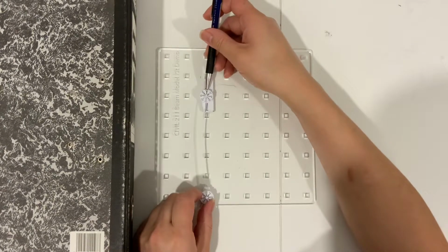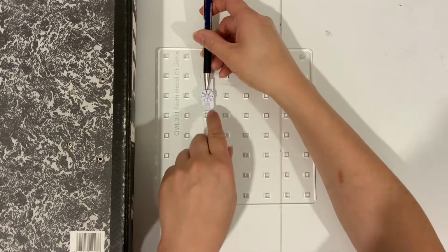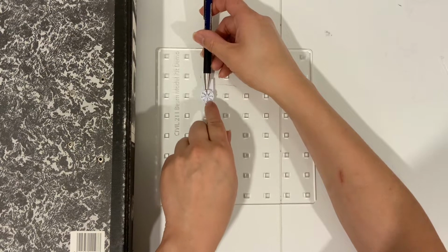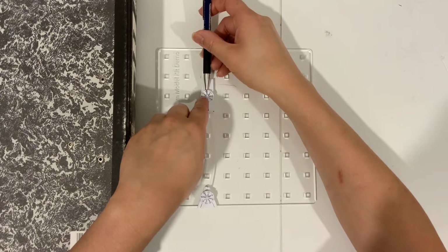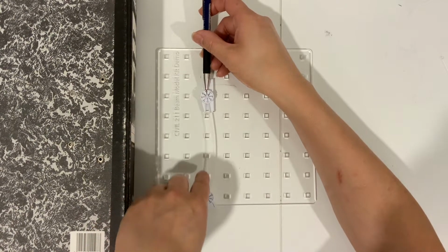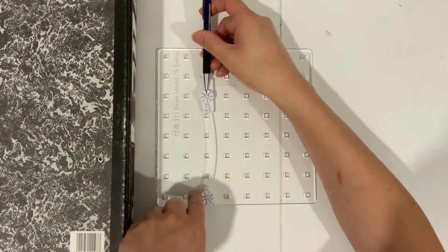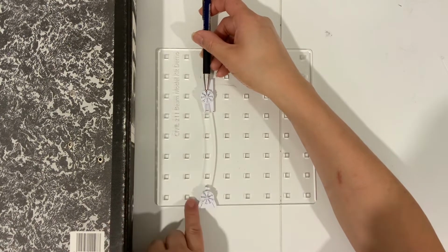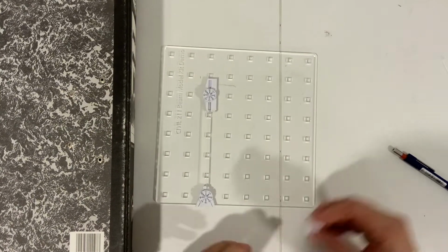Now, if I applied the load down like there, you can see it buckling. So free rotation here, and also free rotation here on this side. And in terms of the length of the sine wave, that's a half sine wave length, which we can see there. So we can see that's called a half sine wave, and it buckles with a length L, or whatever the length of the column is, over that half sine wave.